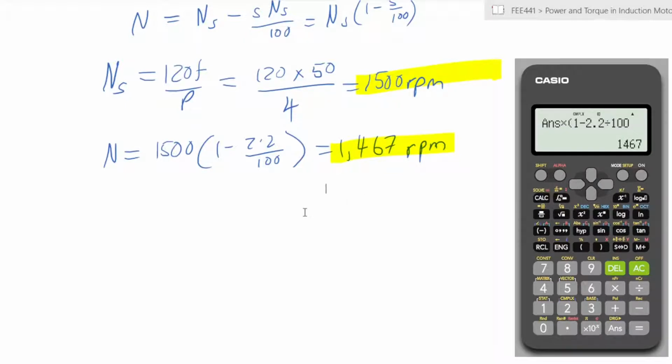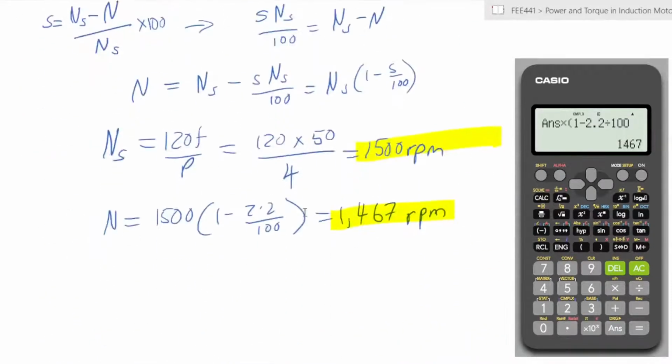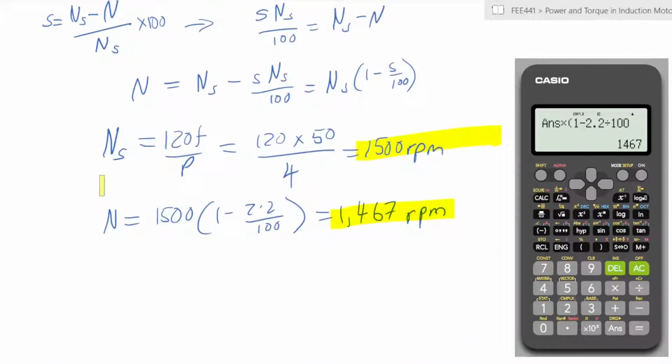And I'll remind you, as I'll keep reminding you, for those of you who will go forward into industry, especially heavy industries where three-phase induction motors are the most used machine, note that your speed of rotation, so the mechanical speed, and the synchronous speed are always closely related to each other because your slip is very small. There is no day you'll have a slip of 60% in a motor that is running operationally or rotating in its normal application, right?